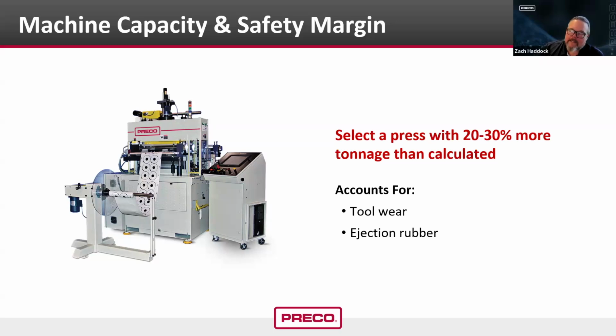The tool wear, as the dies get dull, and they will, all dies are going to get dull. As they dull, that pounds per linear inch is going to go up. And so we need to make sure that we account for that.